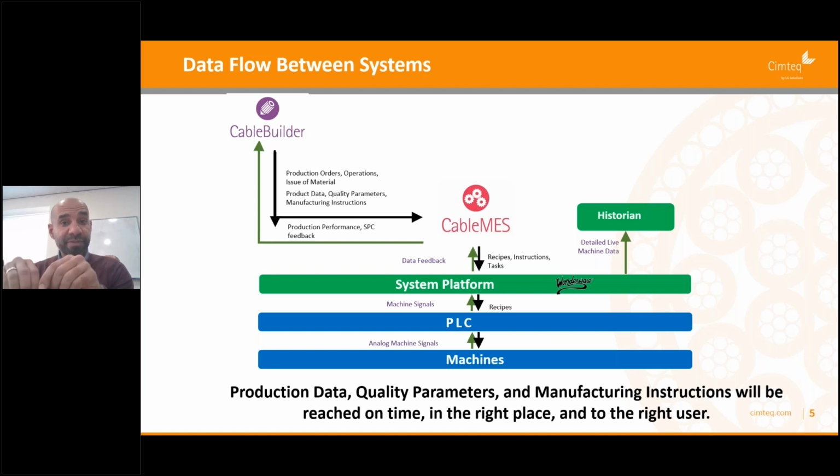And again, I'm just repeating what I've said before. Those small times, getting the raw material ready, getting the drums ready, applying the right speed for the material, getting the quality inspector or getting the operator measuring what he's doing, all those times when you accumulate them, you will see the huge time that you were not noticing before, and you will see the improvement of your line.